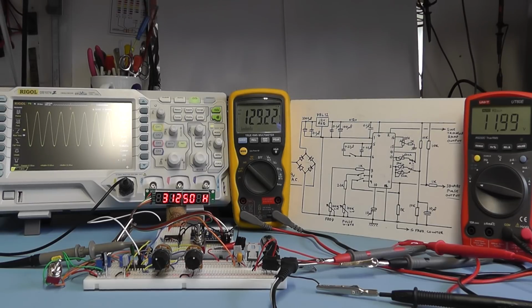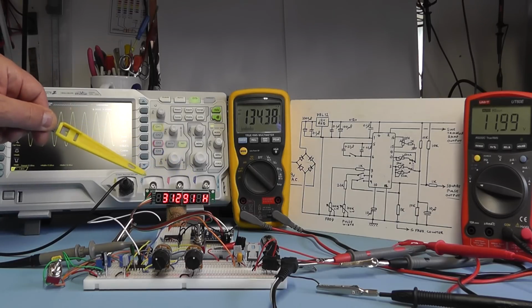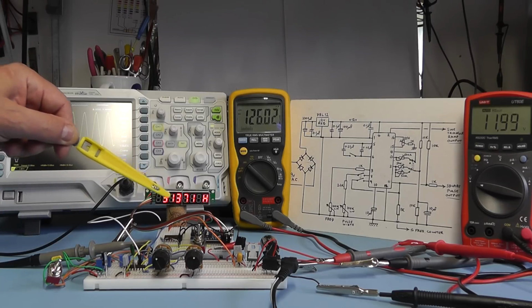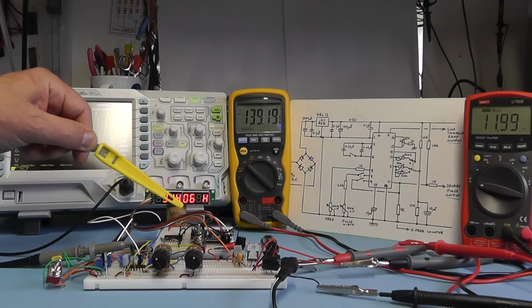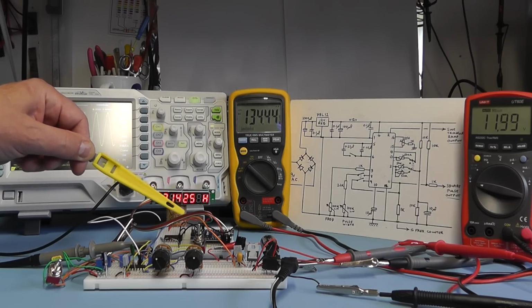What I'm finding is that I can alter the frequency to a maximum of 32,768 Hertz, and the display there works correctly. But once you get higher than that, the display stops, the frequency counter stops functioning. So I suspect that there's an issue with either the software or the way we're using the Arduino Nano to act as a frequency counter.